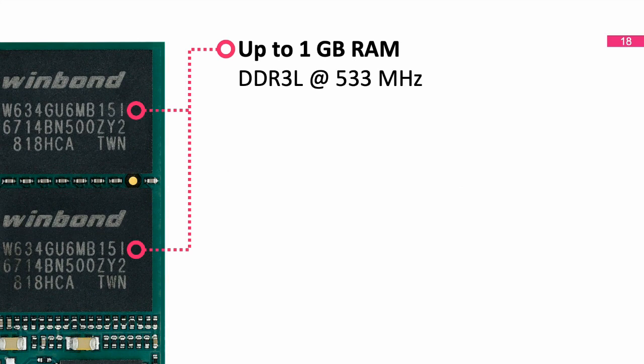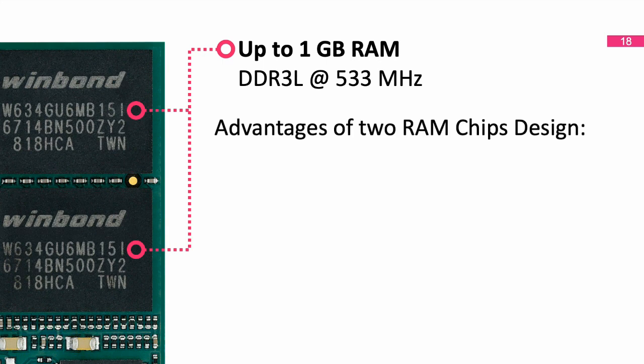When it comes to the memory, we're supporting the maximum of the MP1, which is 1 GB of DDR3 memory. And if you see this picture right now, we've just talked about the main storage and that we didn't include an eMMC or something like this on our board. And you might wonder, why are we using 2 chips instead of 1 chip, right? I mean, there have to be some advantages. And it turns out there are.